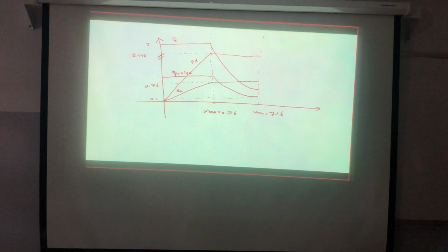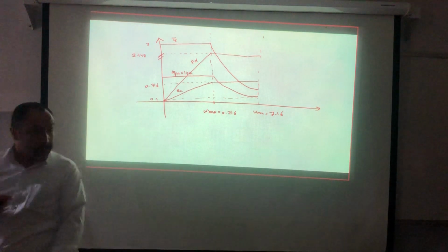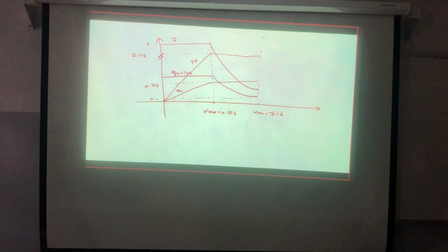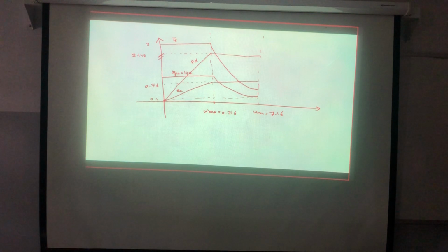Good. So now here, I'm forced to go to the flux weakening before the rated speed. Why? Because I'm allowing the current to be higher than the rated value. Good? And I will stop here. And this is the VA control, and this is what we call the flux control. And thank you for listening.